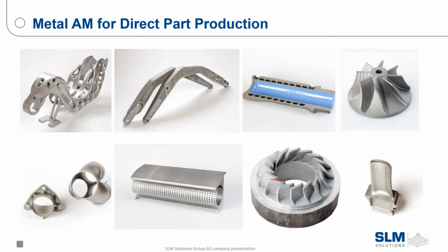Yeah, so right now with the FAA and the infancy of metal additive, each individual machine needs to be qualified separately. That's just how the process works right now. There's just not enough data and not enough track record to say, okay, an SLM 280, no matter where it is, works for this particular part.